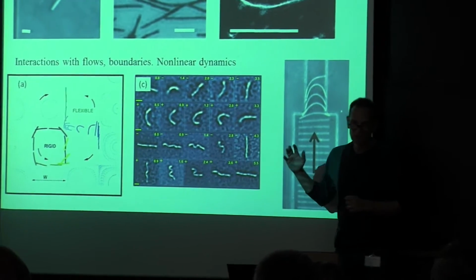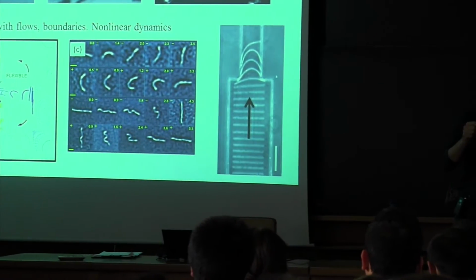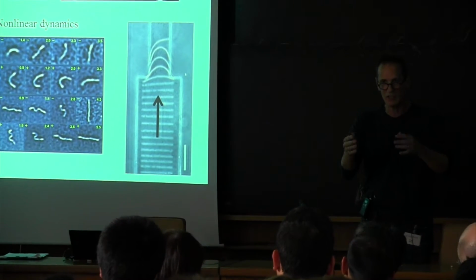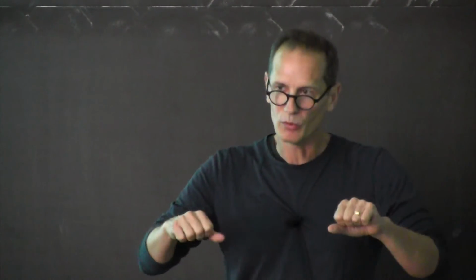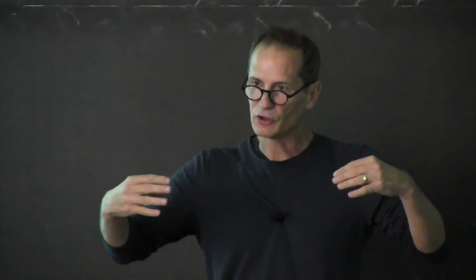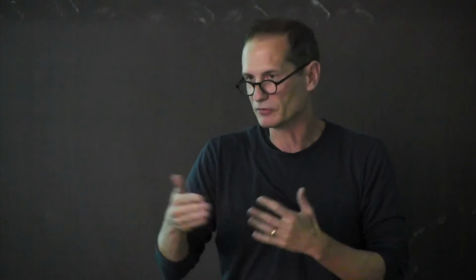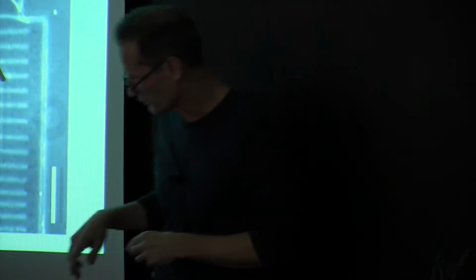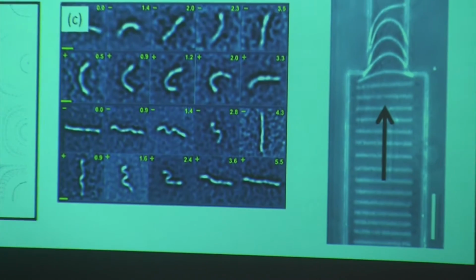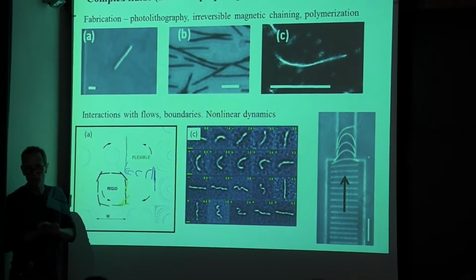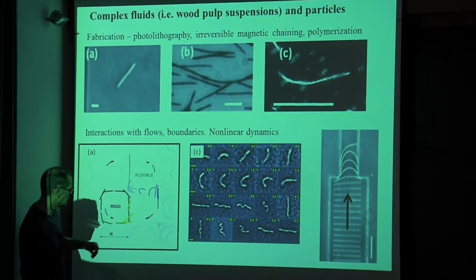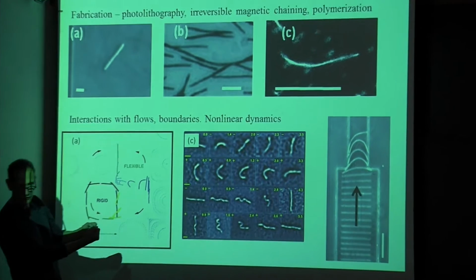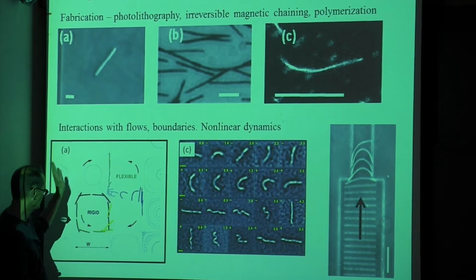These cases are the same but different, because here what happens is when I have a free particle, a free fiber that's floating around, moving around in a fluid, it experiences viscous stresses, right? So I have the fluid is perhaps shearing across it, or some sort of straining along the fiber, and so you have surface loading where the viscous stresses are maybe compressing or extending it because this guy is in some sort of background flow shear. And so these are all kind of surface loaded types of buckling events. And so what happens here is this fiber approaches a stagnation point of the flow along the stable streamline into the stagnation point. You get a viscous loading on the surface, it buckles, and then it goes off somewhere else, buckles again, straightens out, and so on.